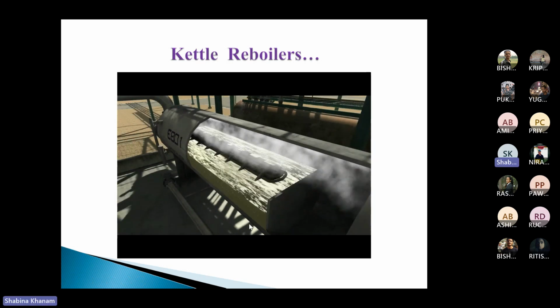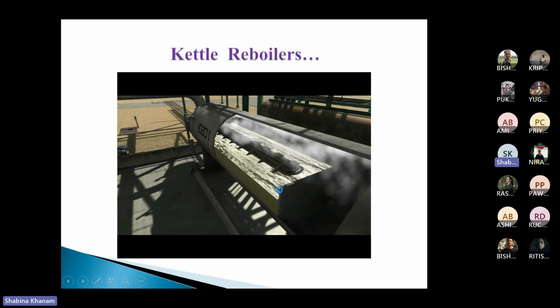So you can see that the liquid starts filling from the bottom, and this section is still without the liquid. If you see, this is the weir. I hope you are getting it. Whenever liquid comes over this surface, it will start coming to this side, and by then this bundle will be completely dipped into the liquid.